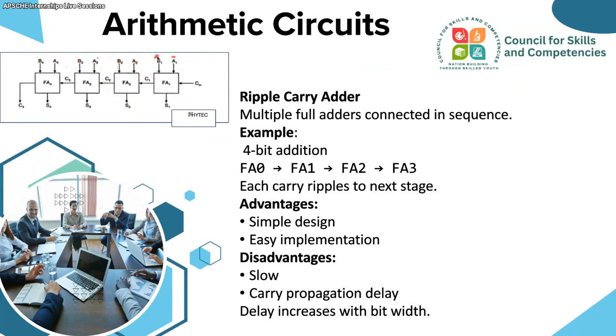So bit 1 of one number, bit 1 of another number, bit 2 of one number, bit 2 of another number. Likewise it will be coming over here, and the carry in for bit 1 we will set as 0, and then once this is completed, when this carry goes inside, you will get the result of this, and the next.